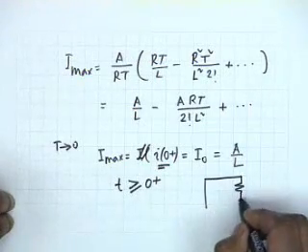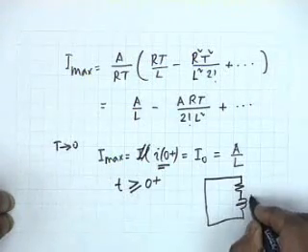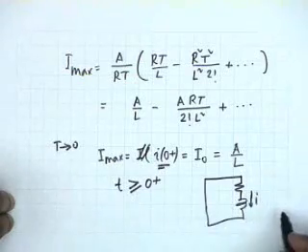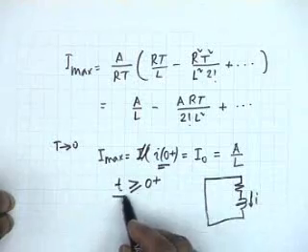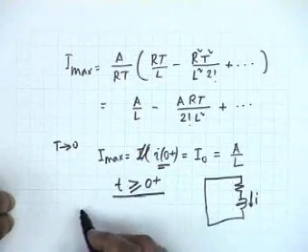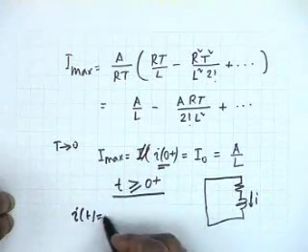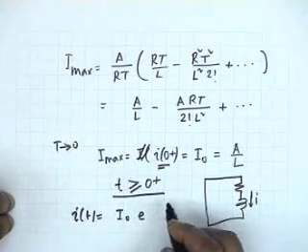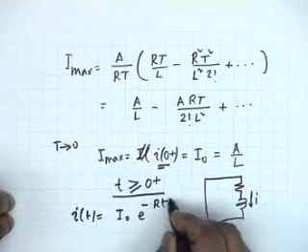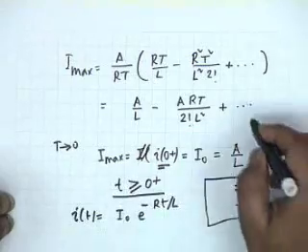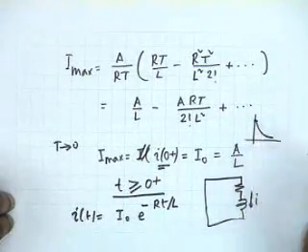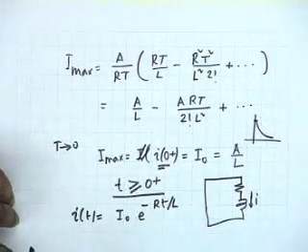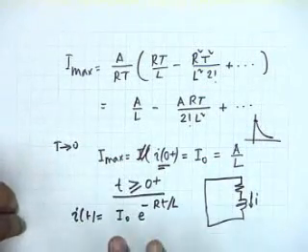In other words, we have R and L, where this current I at 0 plus is equal to I0, and therefore for time greater than 0, the current response shall be simply equal to I0 e to the power minus R T by L, which means that the current response would be, it rises to I0 and then simply goes to 0 exponentially. Is this point clear?